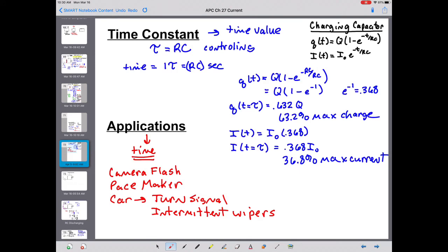What you were doing is dialing up a variable resistor, and that variable resistor is changing the time constant of the RC circuit. And so it's changing how often you reach that voltage that trips the windshield wipers to go on. So a lot of timing circuits use an RC circuit within them to get something to occur at a very regular time period.